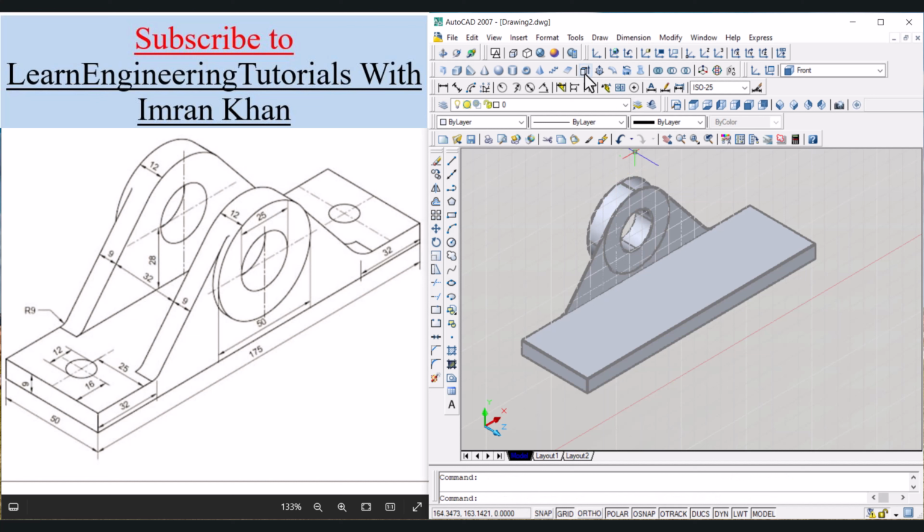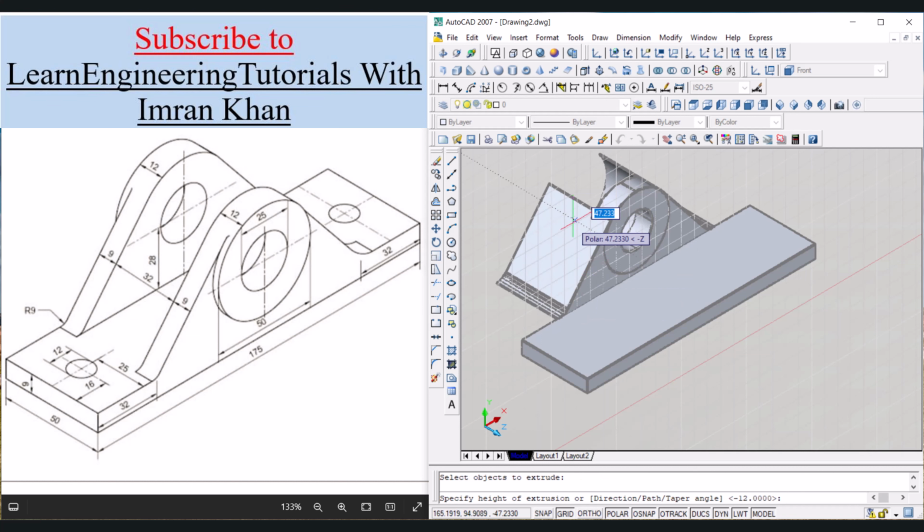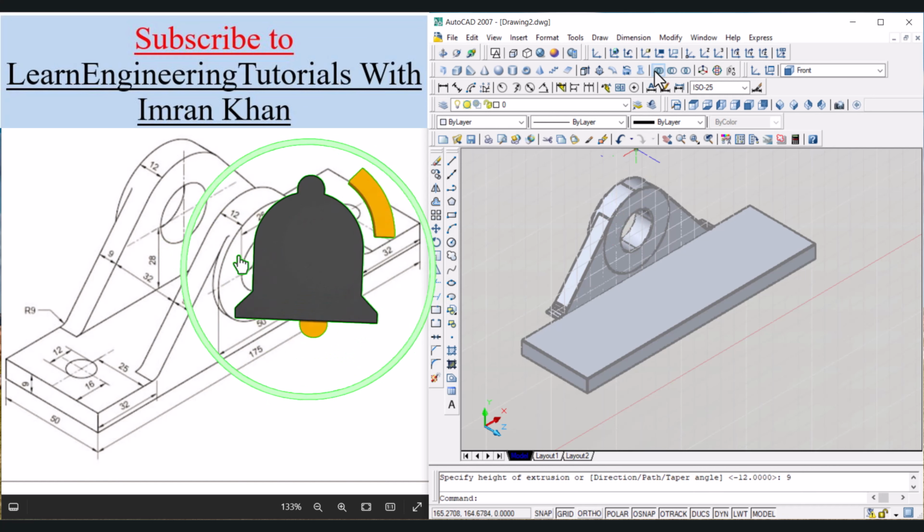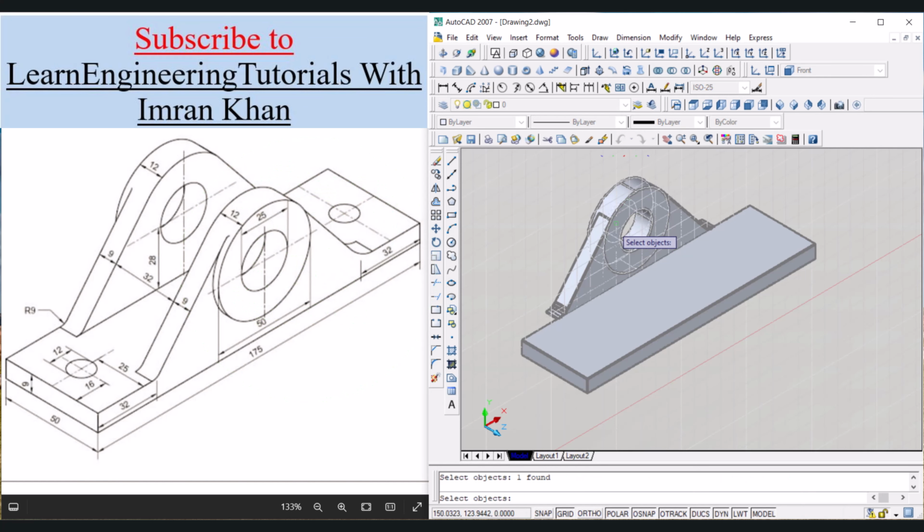Similarly, click on this extrude icon again, click on this object, press enter, and in the same direction give it the value of 9, enter. Now we have to union them, so click on union icon, click on this circular object, click on this object, press enter. Now they have been joined.